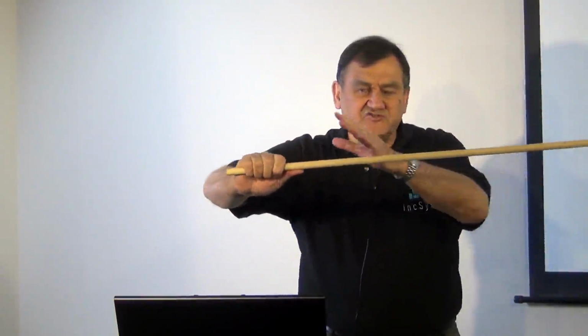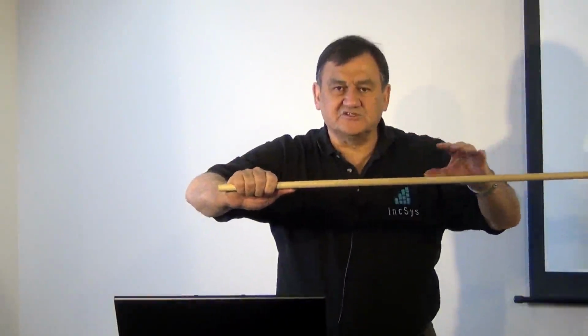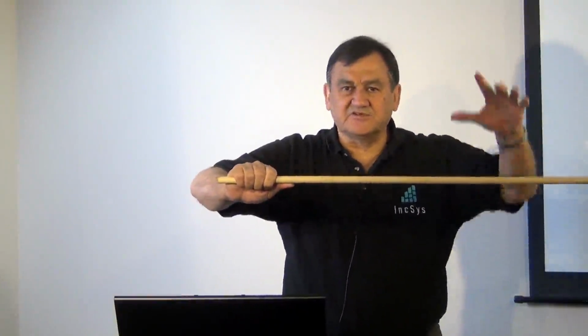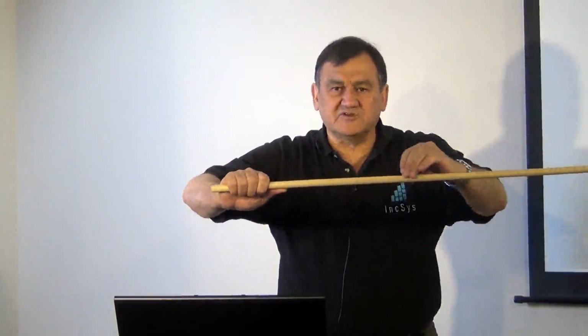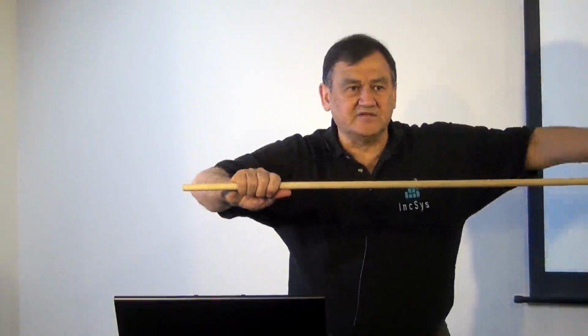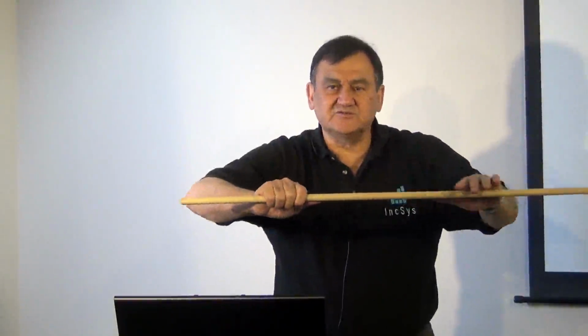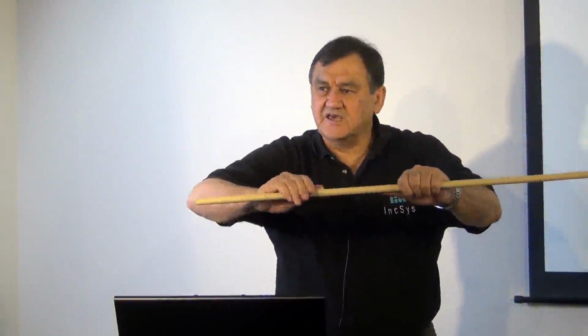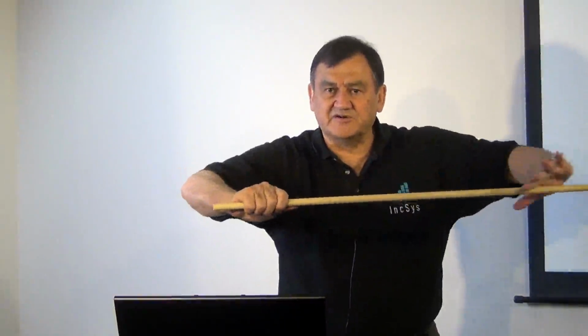And the thing is that those transmission lines can be net producers. They have a capacitance. They can produce megavars. So literally a transmission line at light load will be pushing megavars out both ends. But then as that line gets loaded up, it has a net inductive effect, and it can be absorbing megavars from both ends.